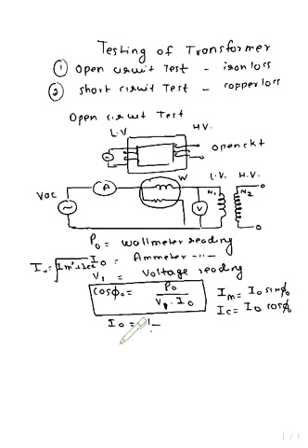Also we can find Z0. Z0 is the impedance of the no load component of the transformer, that is equal to V1 upon I0. And also we can find R0. R0 is the no load resistance.